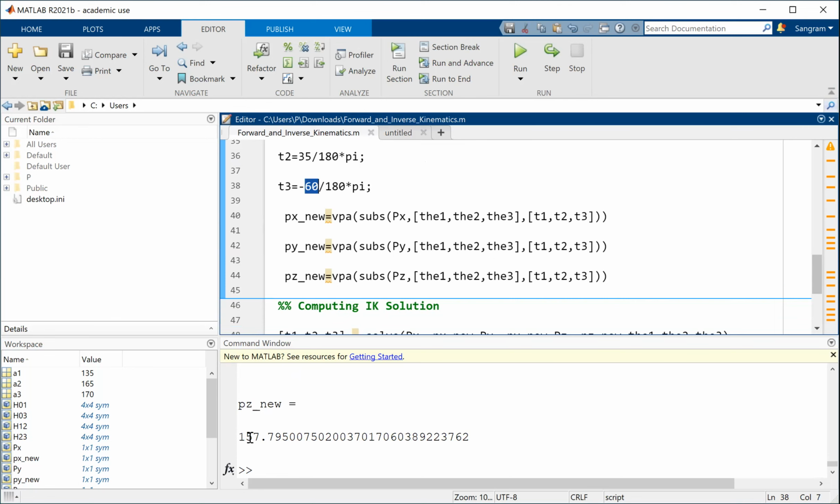Yes. If you use it while actually programming a robot, or while programming an arm, would you use forward kinematics? You use forward kinematics and inverse kinematics all the time. Which would you use more? Basically both, because you generate the equation using forward kinematics and you back-calculate the theta values, based on a simple example.